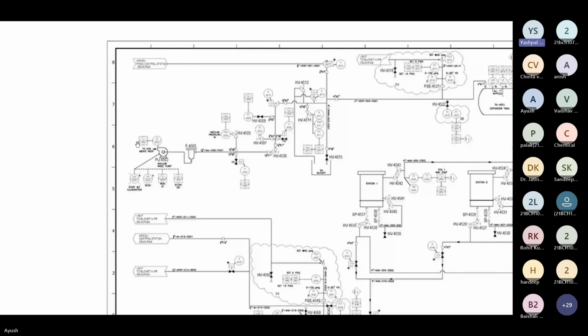In the pump, you can see there are a few circles and squares. These are all the legends for the instrumentation. So in the P&ID, the important thing is legends. Through legends, we can represent the equipments, the instrumentations, and some logics also. There are different uses for different legends, and standard legends are available in the guideline, which I will share with you in detail later on. So you can see the pump with some instrumentation legends. A circle means the instrumentation tag, and a square means further extension of the logic of that instrumentation.